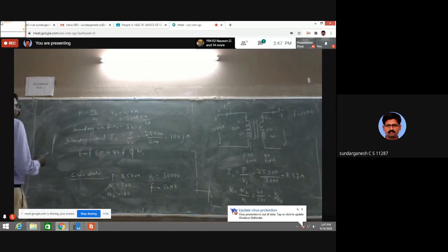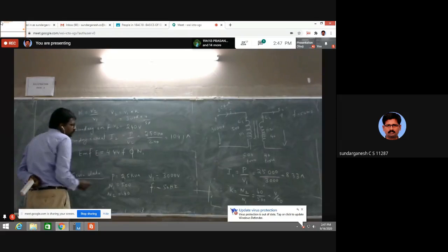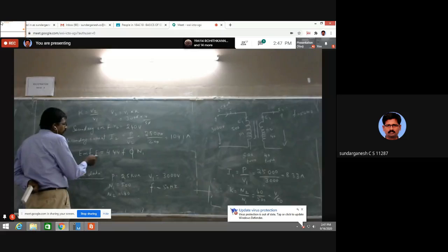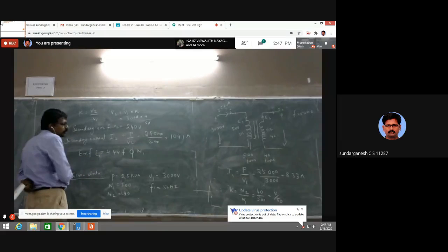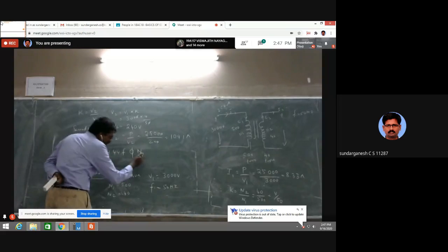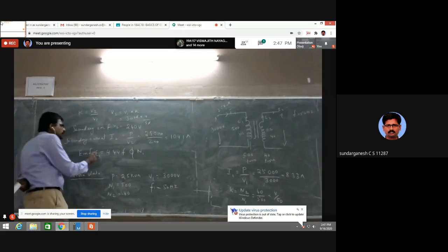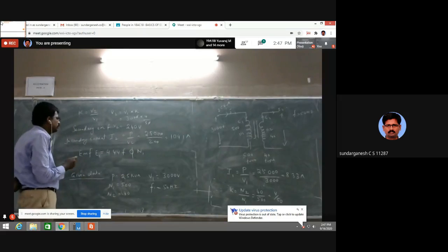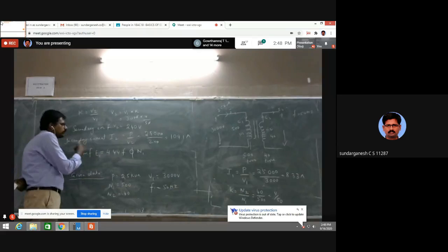We know the frequency, 50 Hz. We know N1 turns. We know the EMF generated. You can take either E1 or E2. If you take E1, you have to take N1. If you take E2, you have to take N2. The corresponding number of turns and the corresponding EMF you have to take.